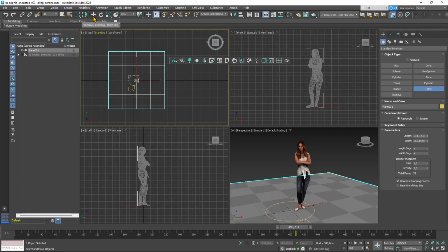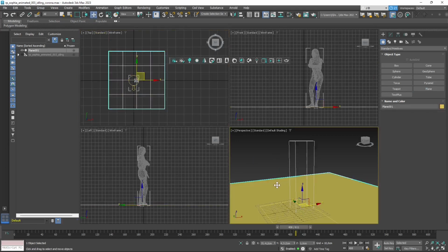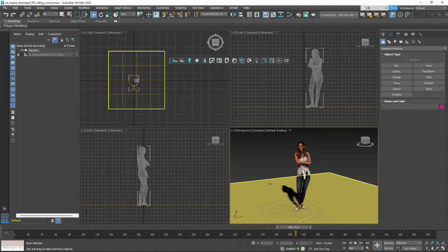And everything is black, so I need at least one source of lighting. Because you can see there is a shadow right there, but we don't really have a light inside the scene, except for the 3ds Max default light, which works with 3ds Max and Arnold, but not with Corona. So we need to add at least one light.